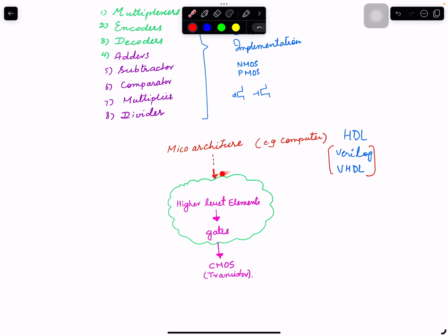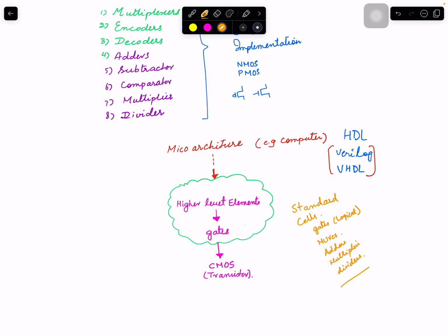Certain gates that we know will be repeated, we design them individually, separately, and optimize them. Those are called standard cells. I touched on these earlier, and they will be important later on. I had a video on standard cells as well, especially for combinational circuits. Standard cells will be simple logical gates. These can be muxes, these can be adders, these can even be very dedicated multipliers or dividers if that is where you want to really optimize. Sequentials are registers and latches, which we will talk about next.